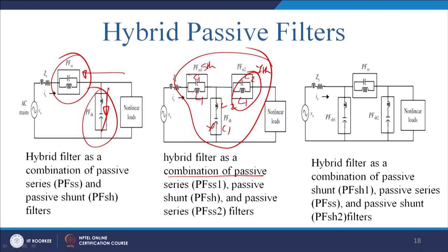In the same way, C1, C2 and L2 can be a sink for the seventh harmonic. So, you are not allowing the seventh harmonic to pass through, and whatever you get will be trapped here. In that way you can improve your power quality problem. In the same way, this is called the pi network.